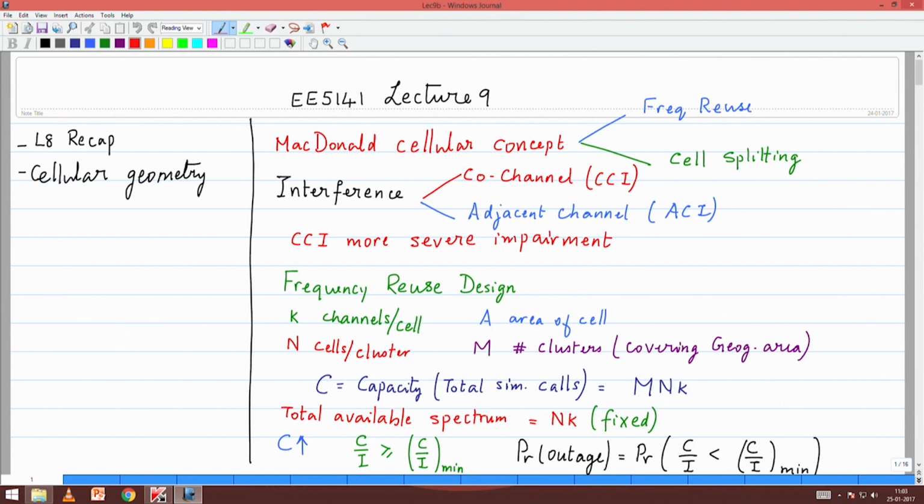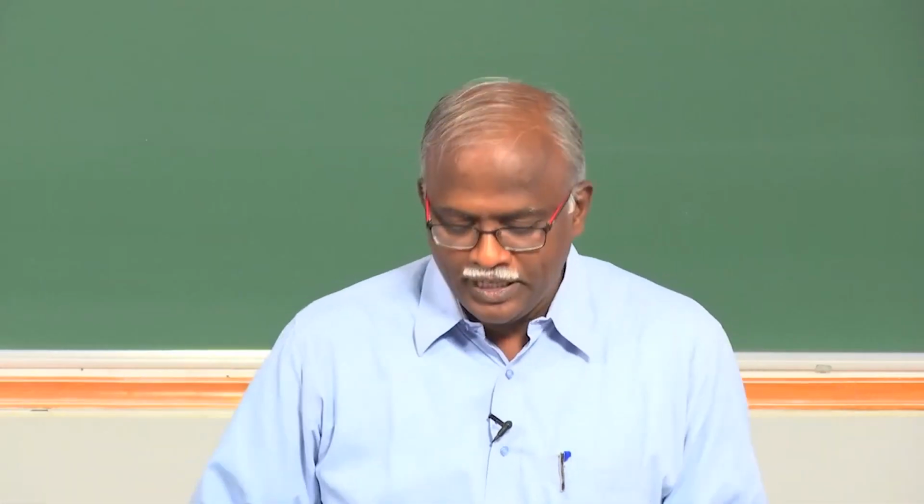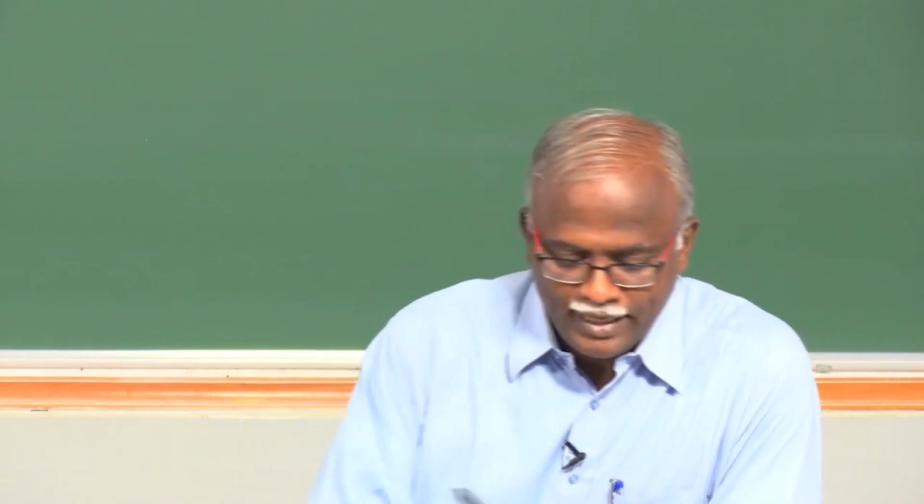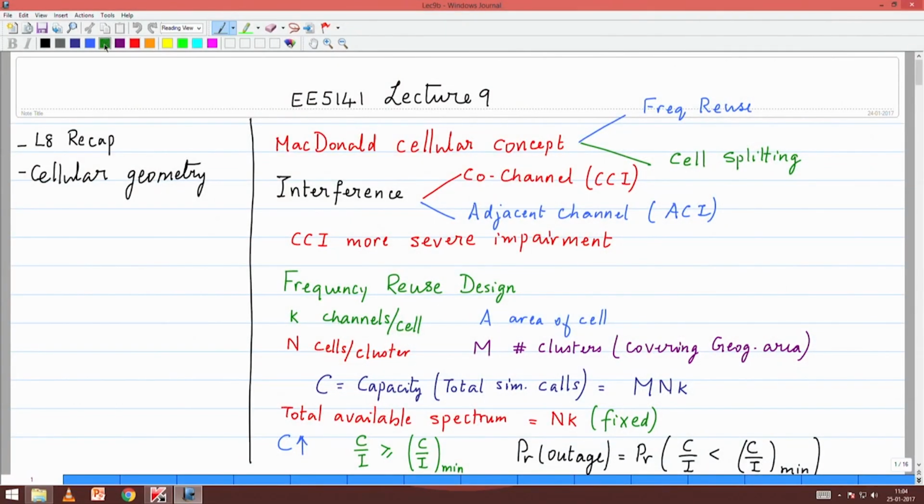When we talk about frequency reuse, we talk about those channels which are exactly the same as our desired user is using. Those would be co-channel users. Then immediately on either side would be the adjacent channel, and then we have the next adjacent channel, and then the others. The adjacent channel ones are more or less handled completely by your receive filter.